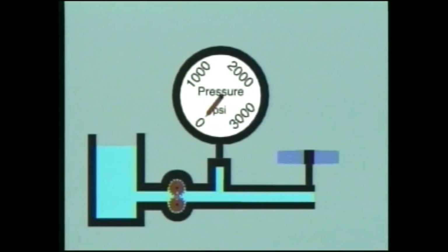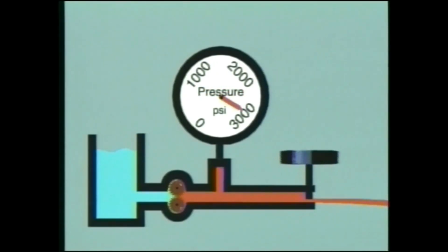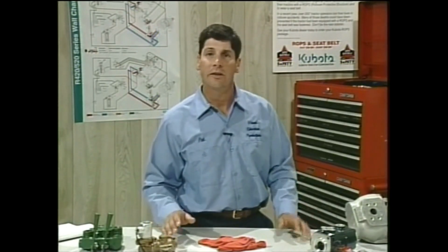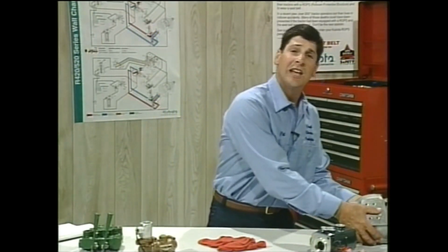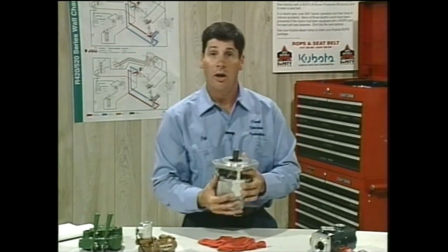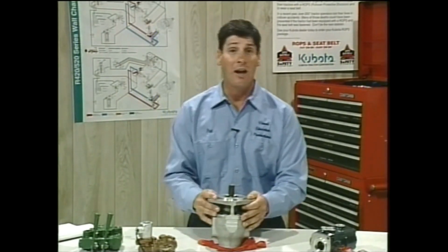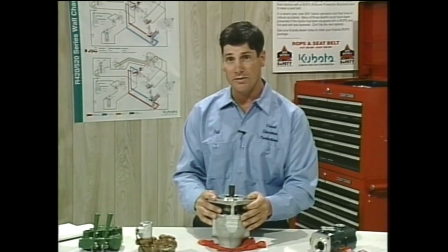As this circuit illustrates, the hydraulic pump is creating a continuous flow of oil. By closing the valve to restrict oil flow, pressure increases. Opening the valve reduces the restriction, thus reducing the pressure. If the pump flow is totally restricted, either the pump must stop rotating or the pump breaks, and all hydraulic functions stop. Keep this principle in mind at all times when analyzing hydraulic systems.